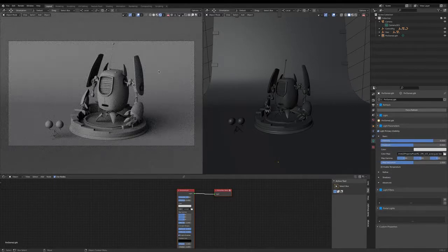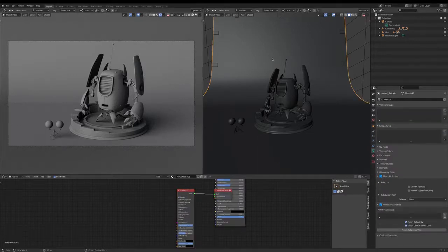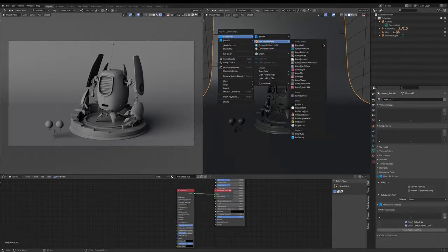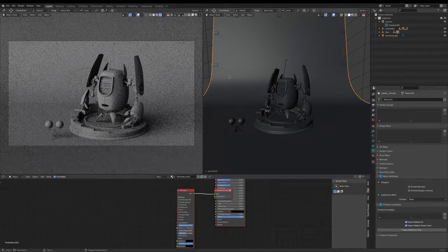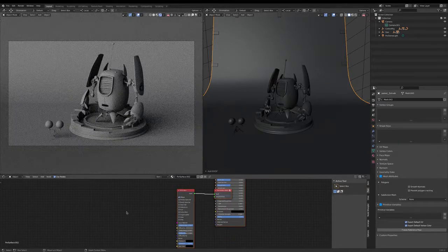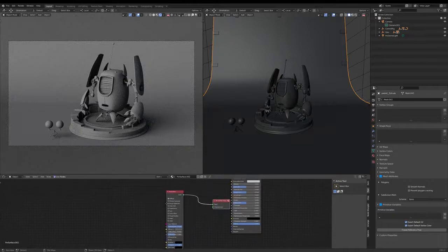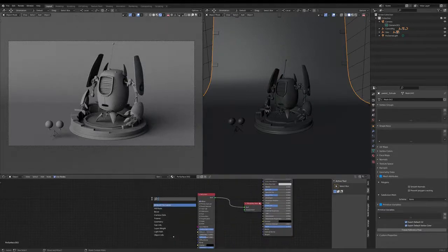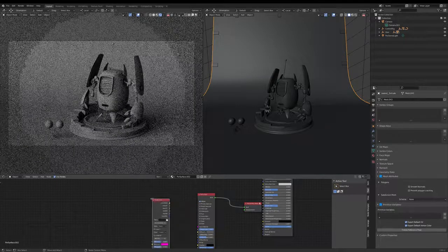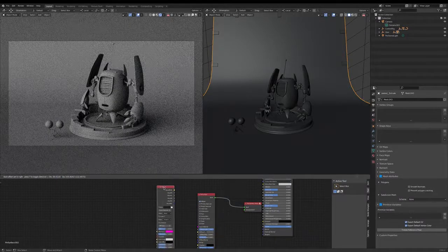So now let's go ahead and start to apply some materials to each of these models. The first thing we're going to do is this background, this tabletop. So I'm going to select it and right click and go add new material and I add a Pixar surface. So that's added a new individual Pixar surface only to this background. I want to add a texture to this, and I do that by adding a Pixar texture node. For all Pixar nodes, you start by typing PXR, and then for texture, you carry on typing texture. And then here we have this Pixar texture node.